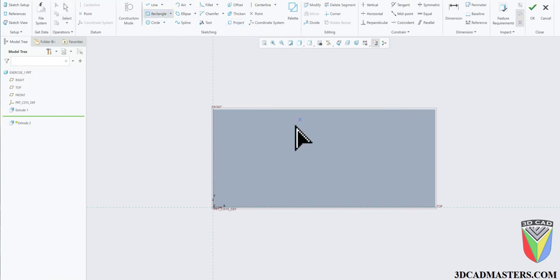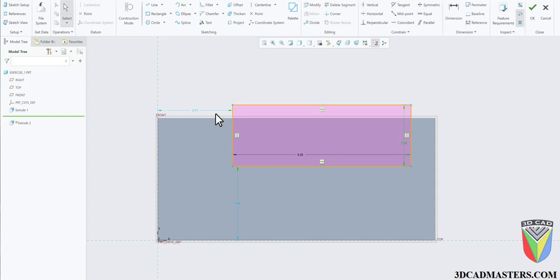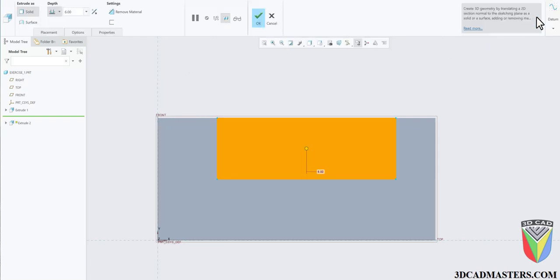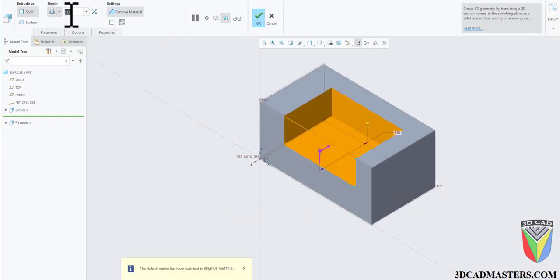Once again, we're going to click the center rectangle and draw a rectangle wherever we please and edit the dimensions here. So on this specific rectangle, you want to edit the dimensions, the positional dimensions specifically, instead of making it coincident to the line on top, so that when we get to our virtual drawing in the future, we can see exactly where that rectangle is positioned. Go ahead and set the depth of this to 8 to match our rectangle's width.